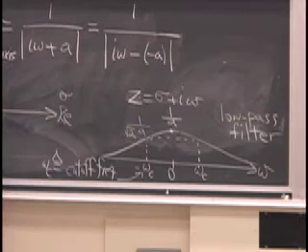And omega C is the cutoff of that filter. So the same geometric type of analysis that we did in discrete time has an analog for these kinds of filters, except instead of going around the unit circle and doing all those vector computations in your head, you go along the i omega axis and you eyeball things.